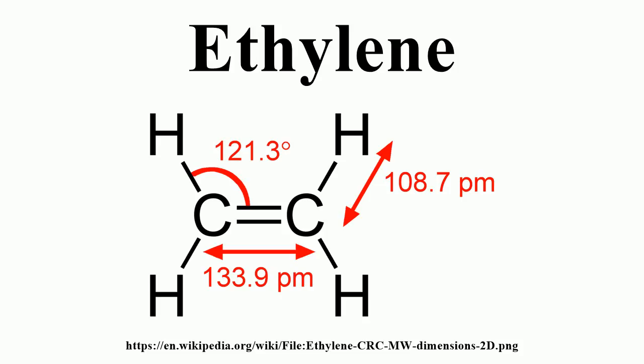The areas of an ethylene plant are steam cracking furnaces, primary and secondary heat recovery with quench, a dilution steam recycle system between the furnaces and the quench system, primary compression of the cracked gas, hydrogen sulfide and carbon dioxide removal, secondary compression, drying of the cracked gas, and cryogenic treatment.